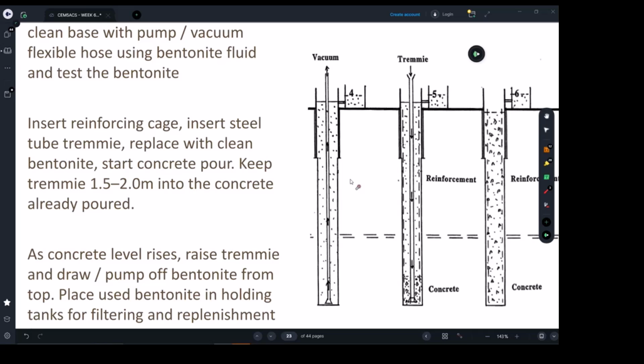Or it can go to 20, whatever meters, if the soil condition is very cohesive, or rock, floating rock situations. If not, you may end up with the CFA method. CFA may still not work if you've got the water table issue and saturated sand issue. Then you have to use what they call drilling fluid.